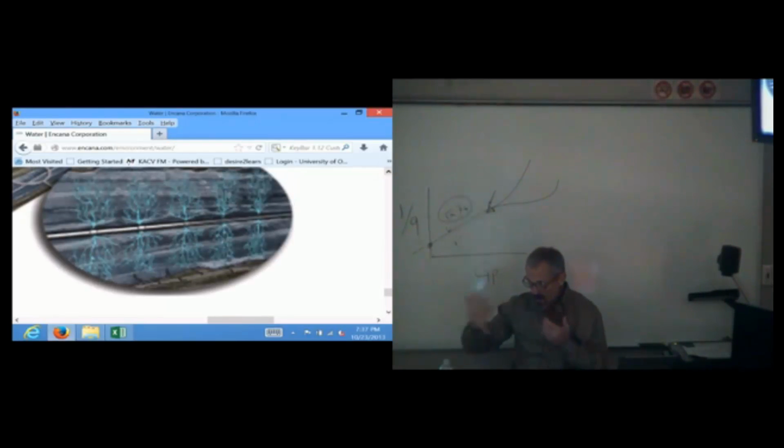Then along that horizontal, there's two primary ways to do this. You can do an open hole or cased hole. You can have plug and perf, which means we've got a cemented liner, or we can do a packer port system where we have swellable packers.